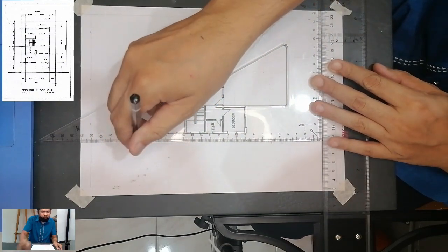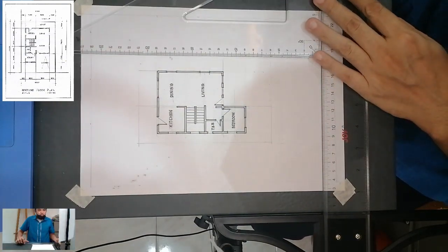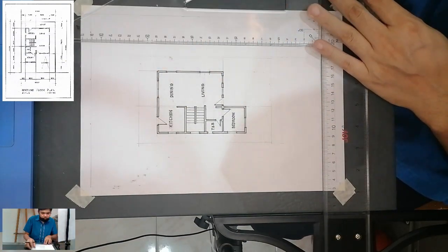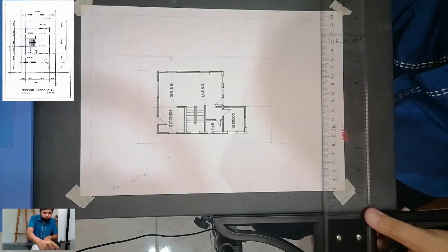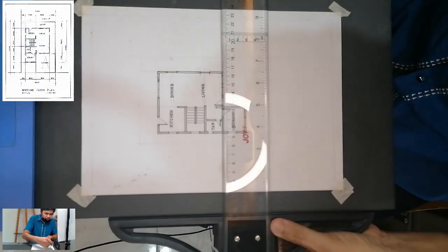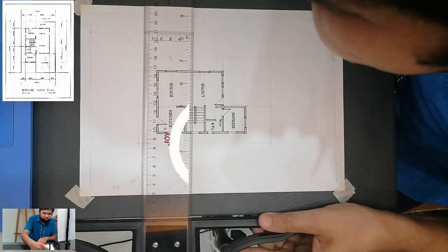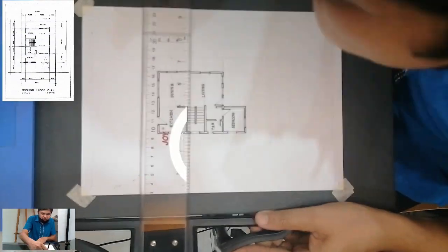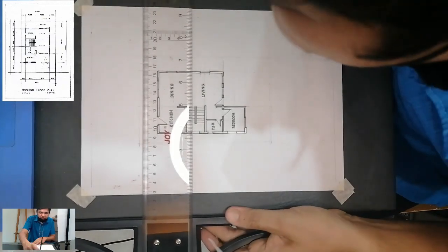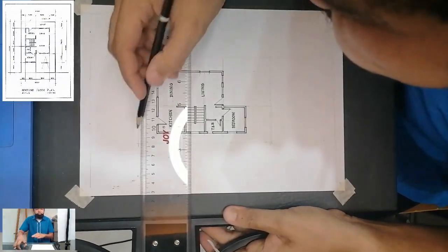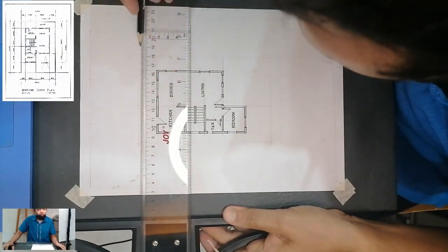So we will first use pencil for us to create the draft for this one. So after the pencil, we'll be proceeding with the inking. So reminder, since it is also a visible line, we'll have to use medium pen or the 0.5 pen.